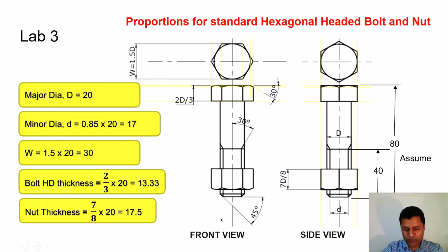So we'll draw the front view. When we have to draw only one view for the bolt, we draw this position. In addition to the front view, when we need the side view, then we draw this view. Otherwise we draw this view. This is given as the first preference, because in the other view it looks like it will be similar to the square headed. So you can't distinguish, if it is only one view, whether it is a square headed or hexagonal headed without the help of the top view. So let's start AutoCAD and draw it in AutoCAD.